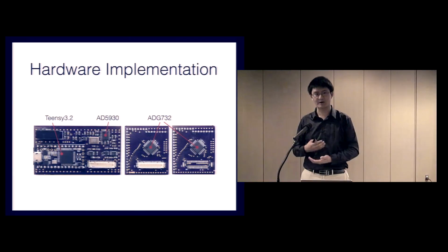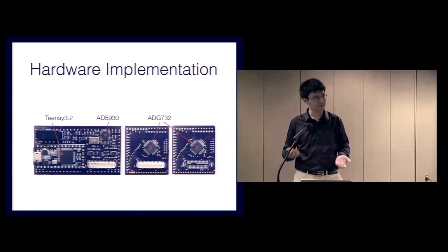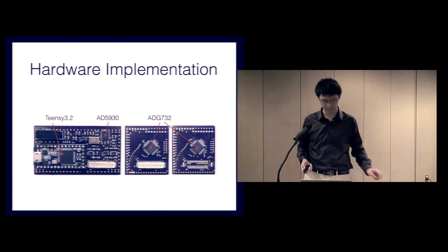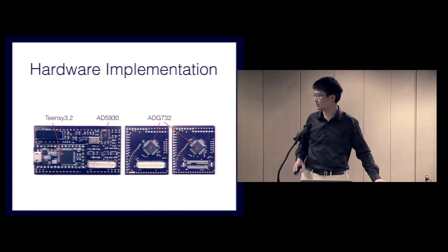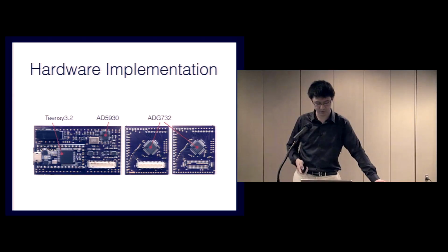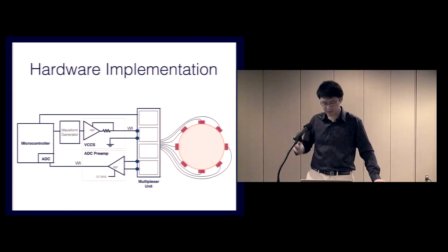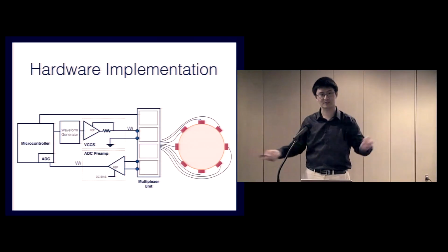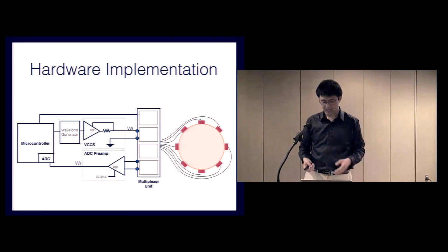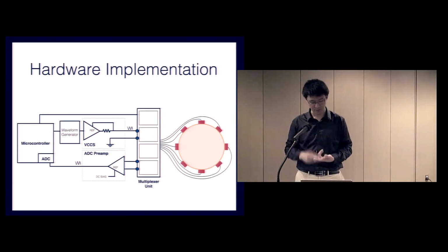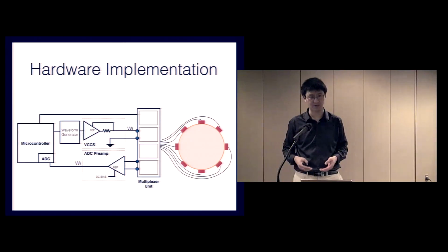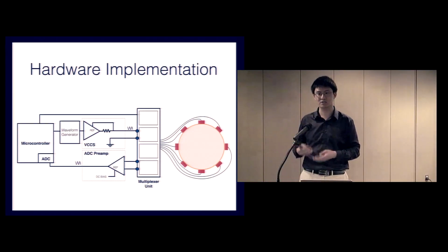So in order to perform our new explorations for our current implementation, we had to implement new hardware to sense faster and implement the four-pole sensing mode. This is just a picture of the sensing boards that we built. Schematically, our system works by multiplexing those electrodes. This allows us to rapidly switch between the electrodes. And compared with Tomo, we optimized the switching time, the ADC read speeds, the microcontroller software, and the sampling methodology to all significantly improve the speed of the measurement system. Details on how we actually achieved that are in the paper.